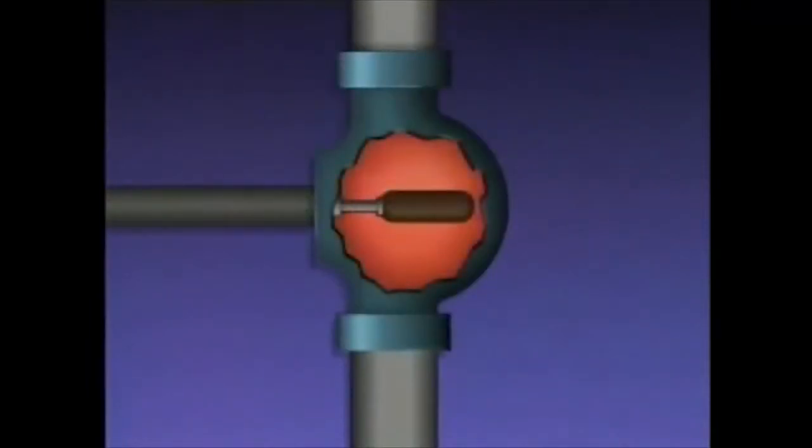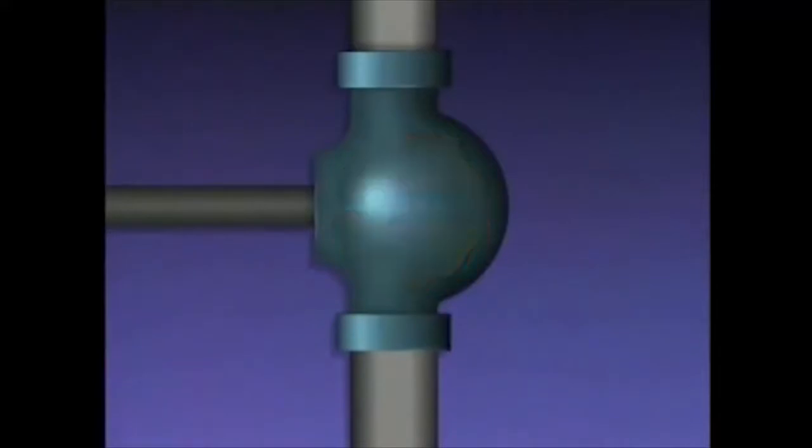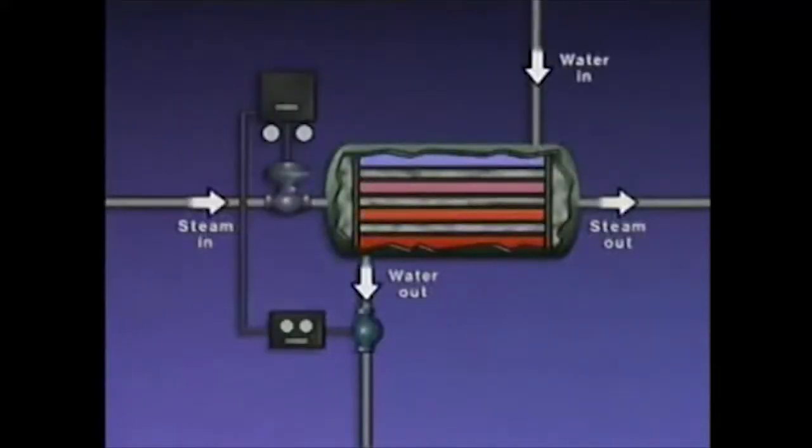There is a temperature sensing device at the water outlet. More specifically, the device is a temperature sensor which contains a gas that expands, and the temperature transmitter will sense it when the temperature of the water leaving the heater increases. The transmitter sends a pneumatic signal that is proportional to the water temperature to the controller.